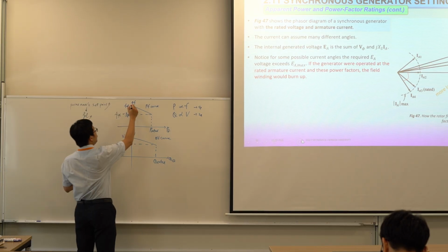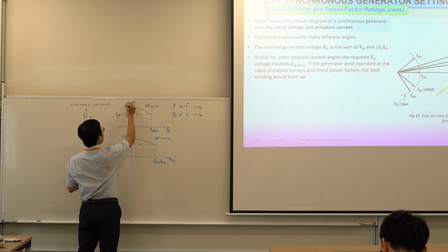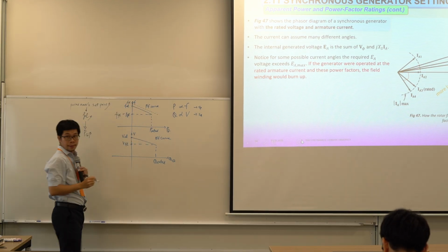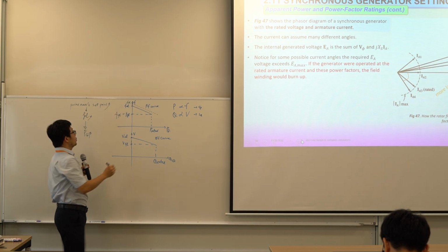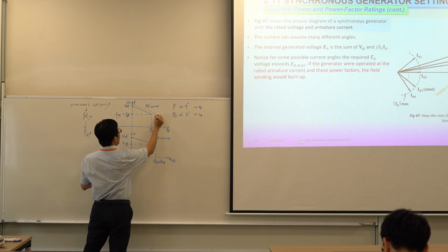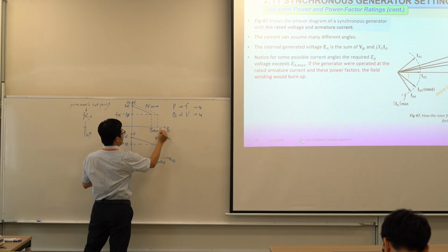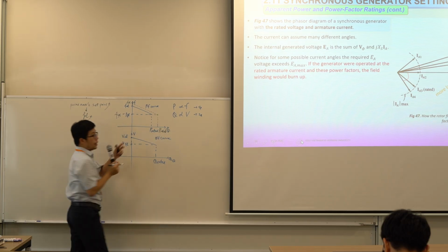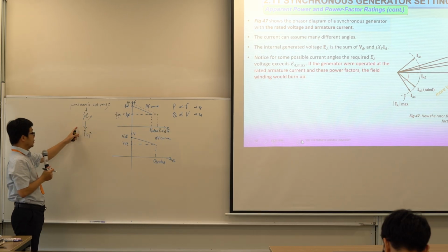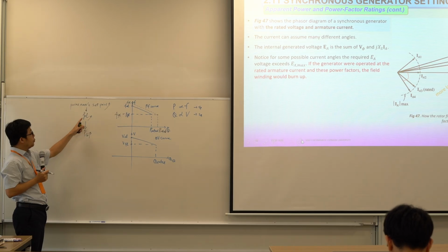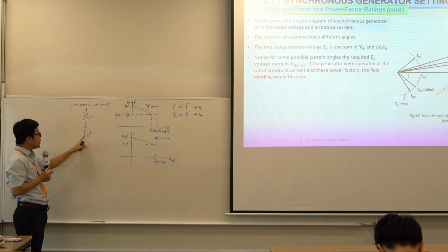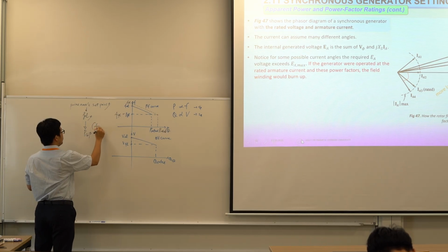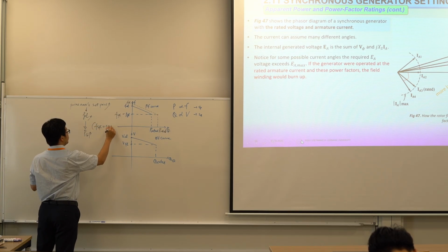So now when we increase F no load, we can get this one. So this is the system frequency. So now we get P rated here, right? So this is consistent with the observation. When we increase the no load frequency, that means we increase the generation power. Of course, F system is constant.